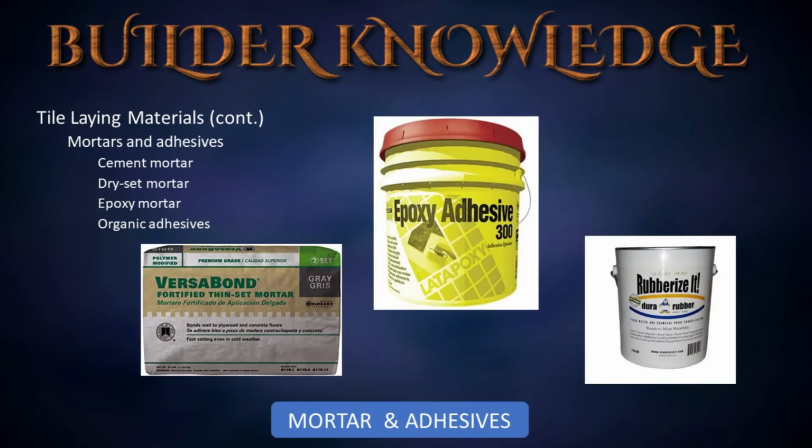Dry set mortar is pre-mixed Portland cement, sand, and admixtures that control the setting time of the mortar. It is not recommended for use over wood or wood products. It provides excellent water and impact resistance and may be used on exteriors. The tiles do not have to be pre-soaked, but the mortar must be damp cured. Dry set mortar provides a bond strength of 500 pounds per square inch.